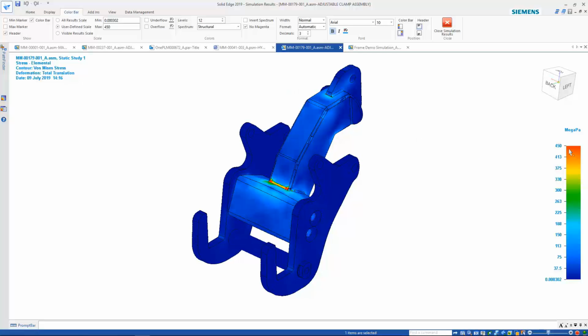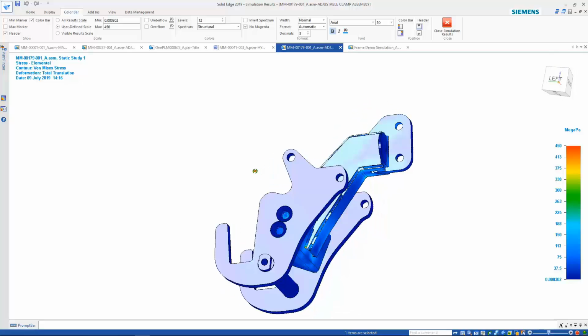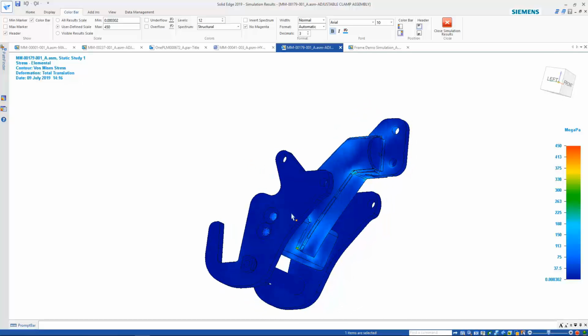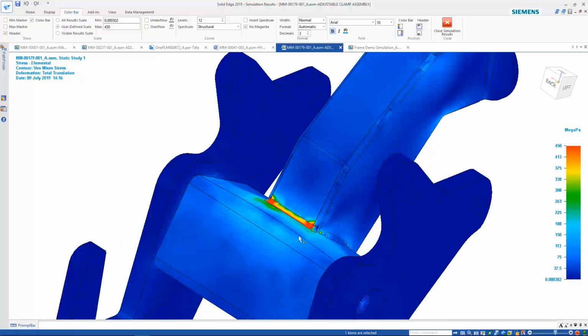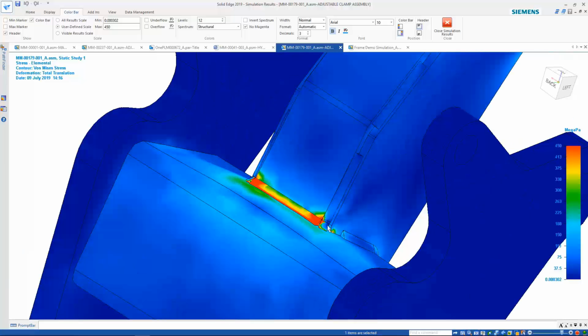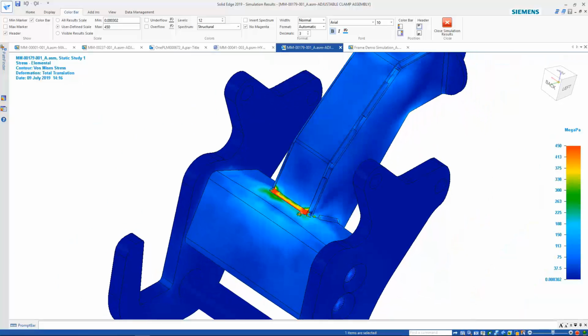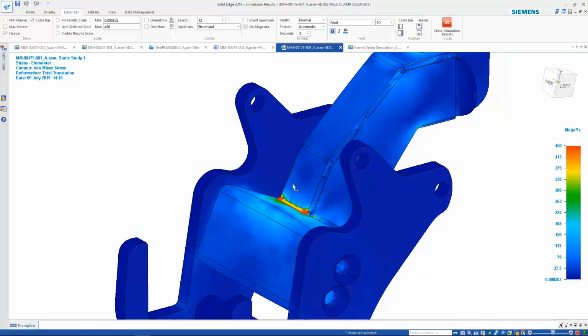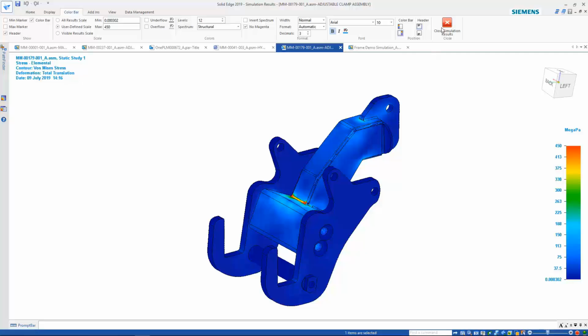So change that value, so we're only showing up to there, and it's going to show us much more where those are. We can see straight away that we've got slight compression issues down there, a few issues on the back there, but most of it is around these welds. I've actually done the weld stitches on here, which we could simplify the geometry and get rid of, so I wouldn't be too worried, but it might be worth putting an extra couple of ribs just in that place to get that how we want.